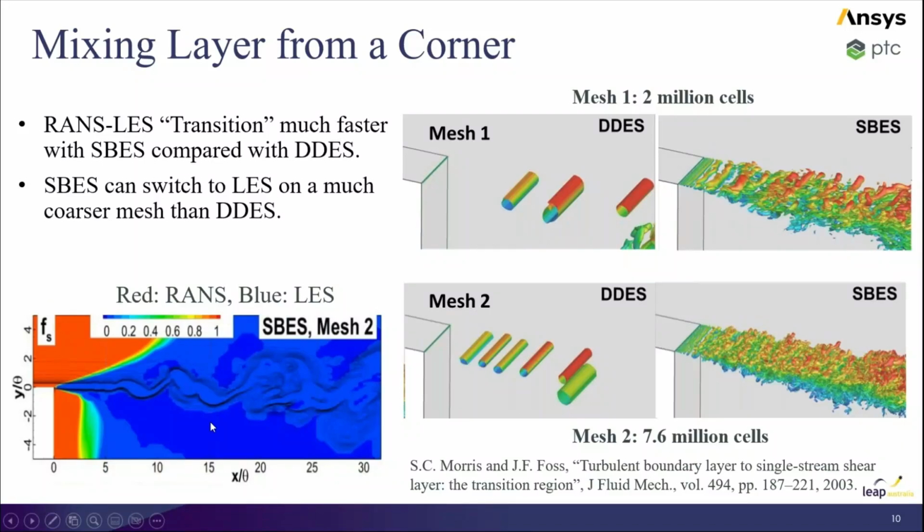So you're now using the best of both worlds, because you're using the RANS model upstream here. You can do your LES here, and later on, if we have a coarse mesh near the exit, this could easily transition back to a RANS solution, which is good for passing out an outlet, because you won't have all these complex eddies trying to go out an outlet. You'll just have a much simpler flow. So this is essentially where we're at with these type of models.